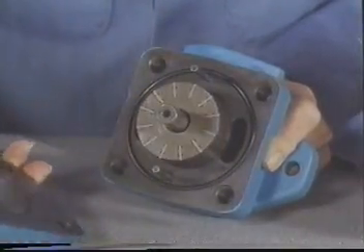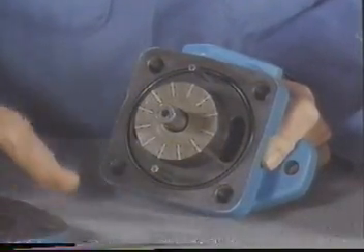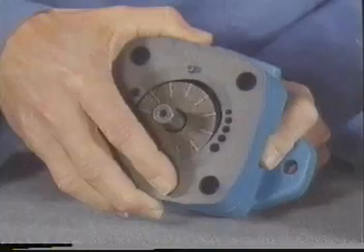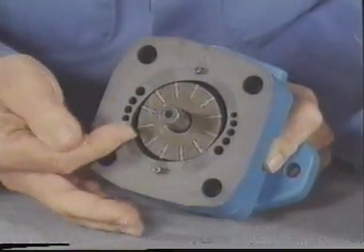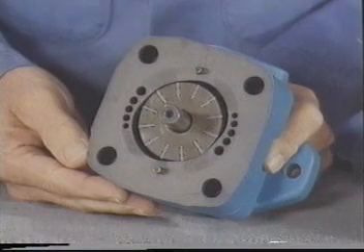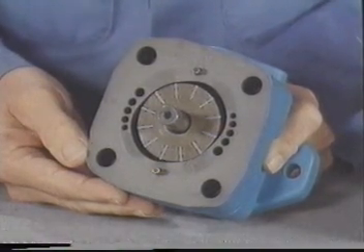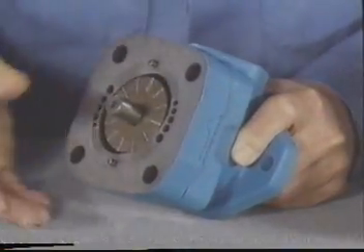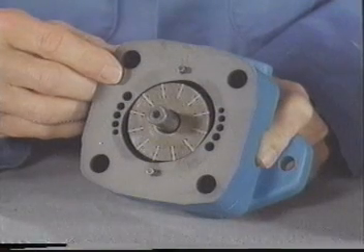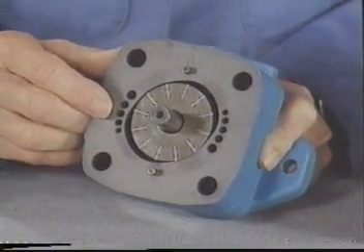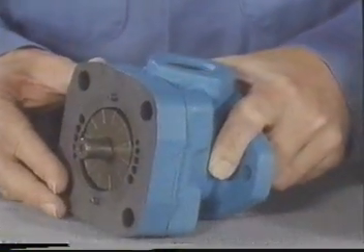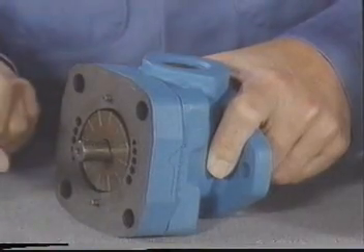Pump rotation is established by the position of the cam ring. Removing the ring from the locating pins and replacing it with the opposite side facing the pump body automatically rotates the cam 90 degrees, and the pump may be driven in the opposite direction. Arrows on the ring indicate proper rotation. The varying size holes in the ring are called overpass holes. They improve pump inlet conditions by permitting oil to flow into the cartridge from both the body and the pressure plate side. Reassembling the pump is equally as simple.